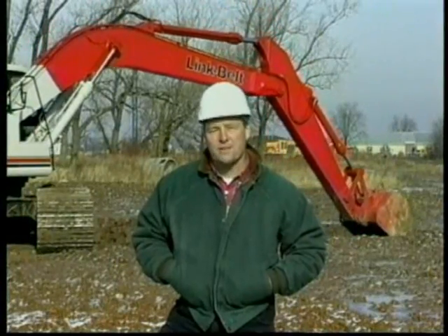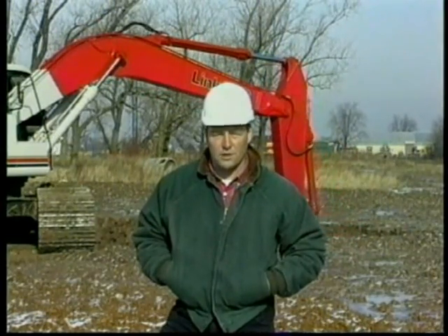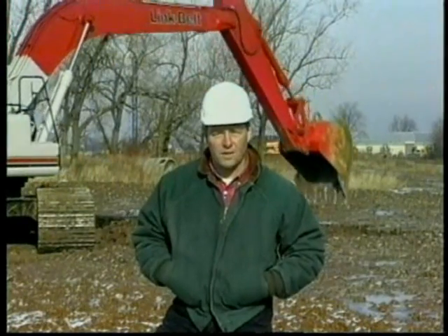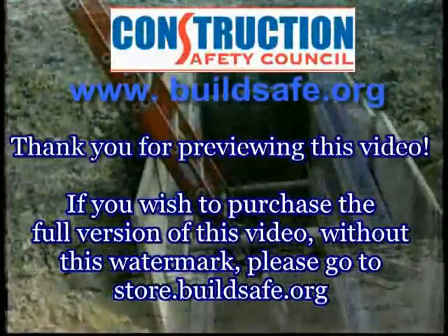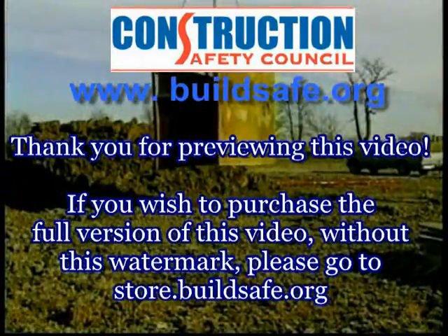The competent person now has collected a large body of information: the soil type, the location of utilities, the size of the equipment available, the space available at the site. The competent person knows the depth and size of the excavation and is familiar with the protective systems. Now the appropriate protective system has to be selected to protect the employees who will work in the excavation. These protective systems could include sloping or benching, shoring, and trench shields.